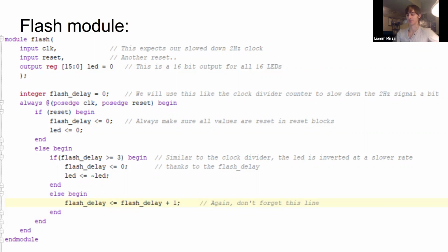If you're at a point where you're missing a module, then something's gone horribly wrong. For me, it was usually a parameter missing somewhere, and I had to hunt down the file that had it. The most common thing I've seen was misspelling the module when you're instantiating it. Then Vivado will say, I don't know what module you're referring to, but this is a very similar name, so I'm just not going to use it.